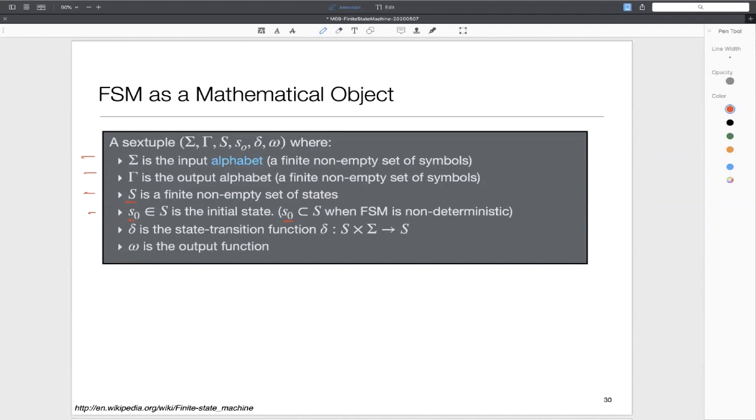And in that case, the state machine is referred to as being non-deterministic because its behavior depends upon where you are starting. For example, if the hardware powers up, then the state vector, the state bits, are arbitrary. If you don't do anything special, most hardware could start in any state. So usually in hardware, we provide a reset signal to force the hardware immediately into a particular state so that we can have a deterministic behavior. It turns out in computer science, there are valid reasons why people like to think about non-deterministic FSMs also. We would not worry about them here.